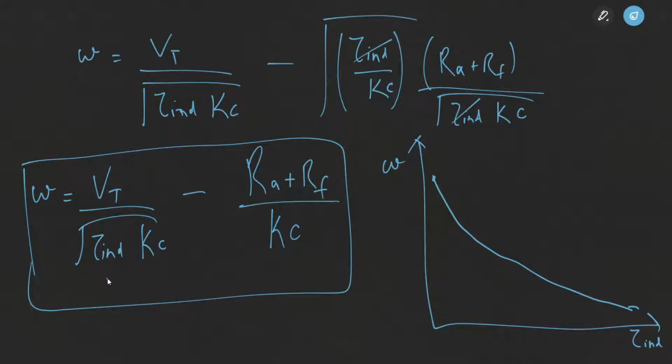Fine. So we are starting from this point instead of starting from here, because you can see if torque induced is equal to 0, if we substitute torque induced equal to 0 here, this term will become infinity. That means speed will become infinite. For a series motor at torque induced equal to 0, the speed is infinity. So what does that mean? That means the motor will be seriously damaged if we are actually unloading the system